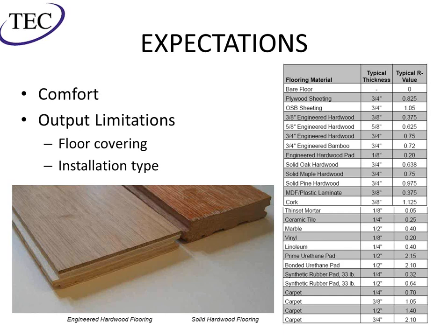And if you're not using the aluminum plates, it's even worse. The other thing to consider is the floor covering. With a wood floor, they may only be able to handle certain temperatures, so that could be a limiting factor in how much heat you can get out of it.